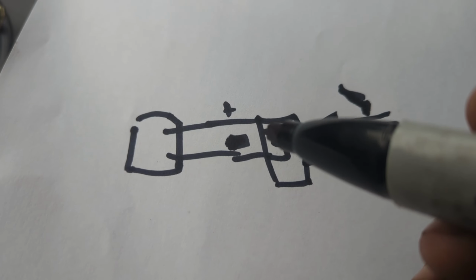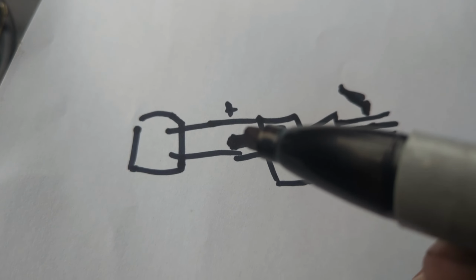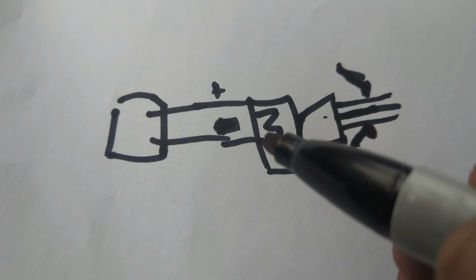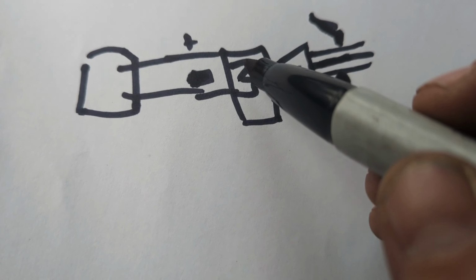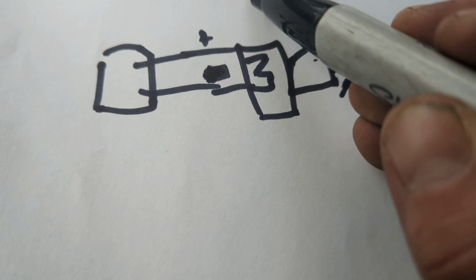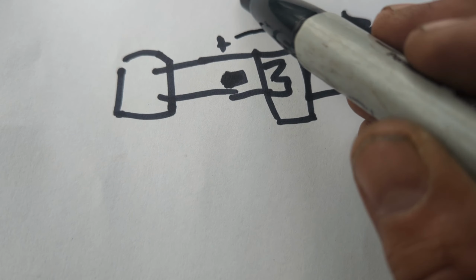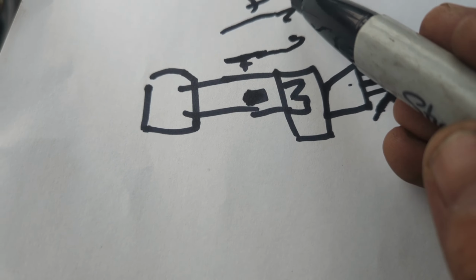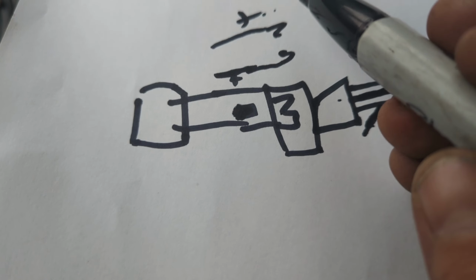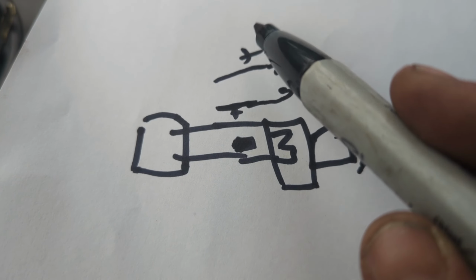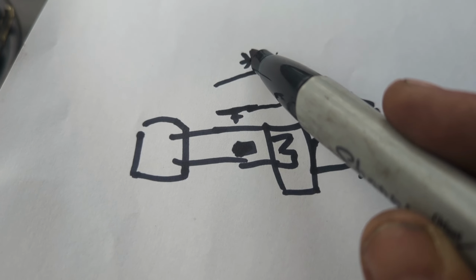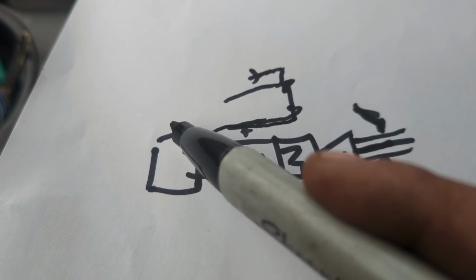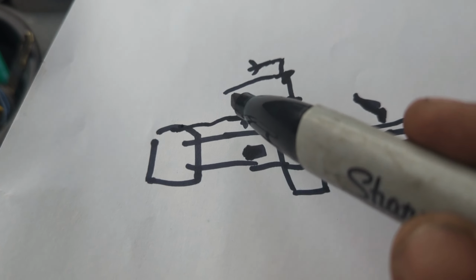Now, the high voltage code that we are getting is because, after this igniter ignites, think of it as now there's an open in our wiring. So what we probably have is a 12-volt bias voltage being sent out and pulled down to the ground. When there's an open in the circuit, it's unable to pull that bias voltage down to ground. So then all we see is 12 volts on the signal line when it should actually be 0 volts.